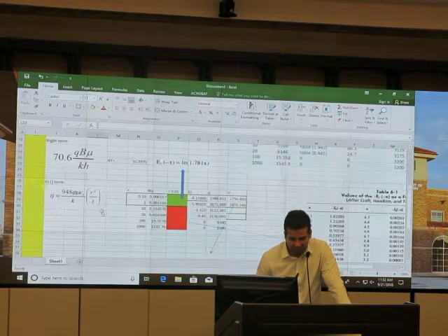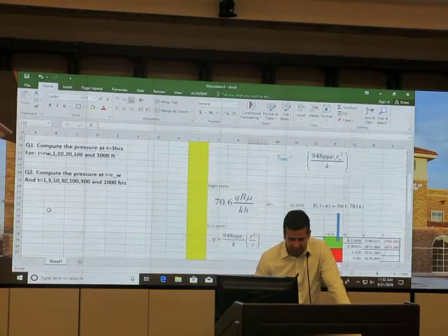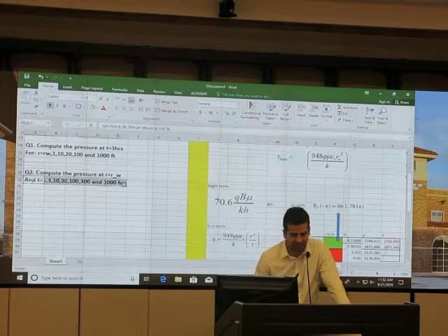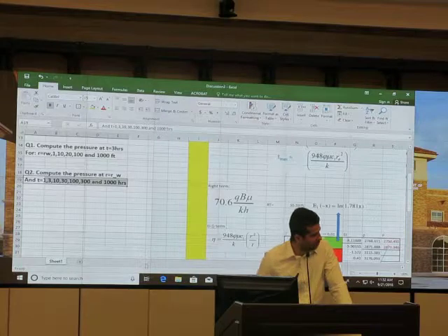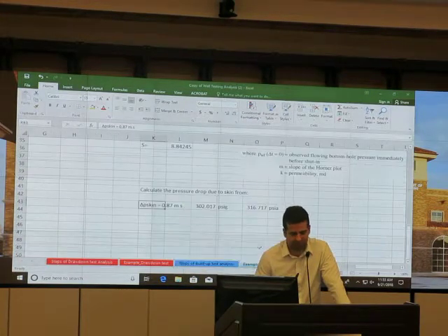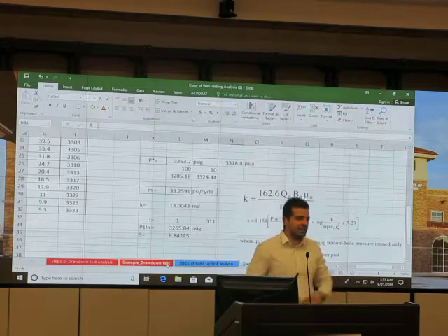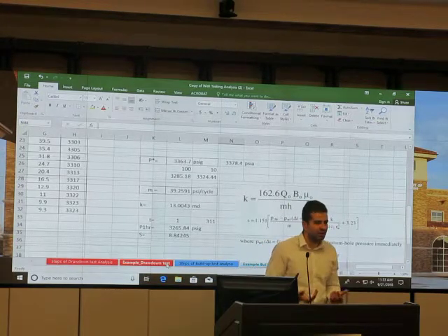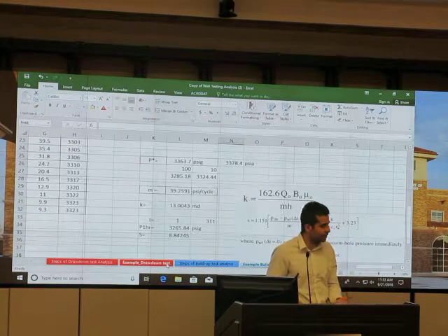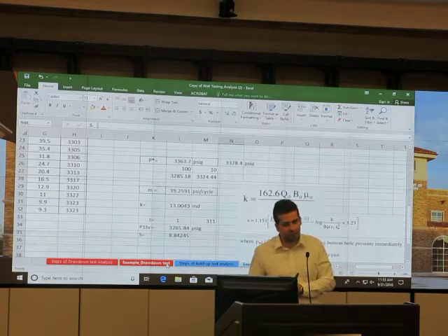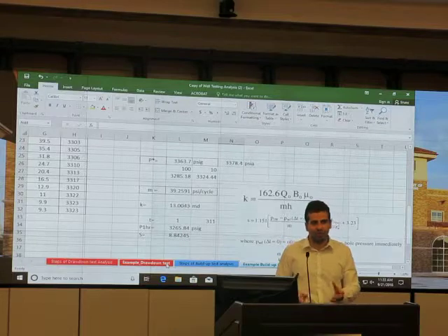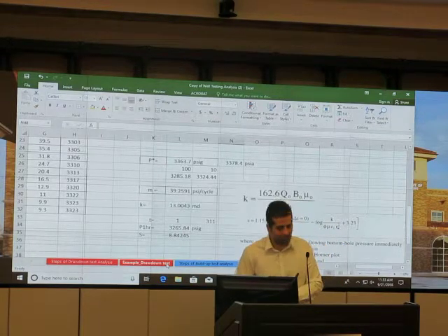Okay, so I was going to have you do the second part, which is to have the R the same as RW and calculate T. Please do it at your convenience, because I want to talk about the build-up test. So it's simple again. You have the EI formula. This time the variable is going to be T, and your R is going to be the same. You do the same thing. Calculate mu, and then you calculate the EI function, and you get the pressure drop, but for different times.